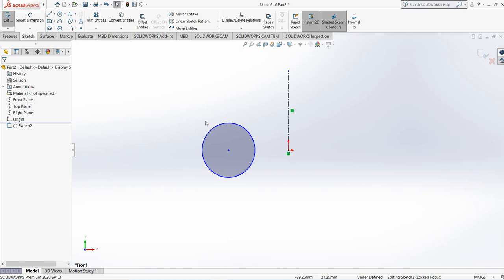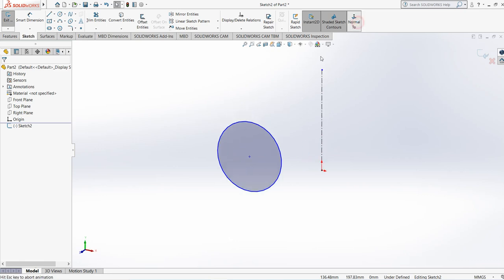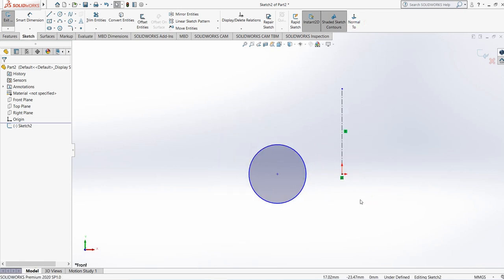So let's just imagine it as a 3D view. So it will be in a donut shape if it revolves around this body, right? If we make the circle revolve around this center line, it will be like this and complete 360 degrees. So for the revolve tool, what we need is a sketch, a closed entity for the solid body or for the thickened sketch, and also a center line or any edge. So we will get back to the any edge option.